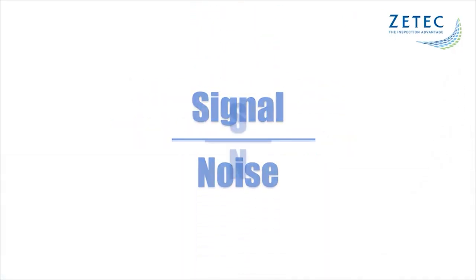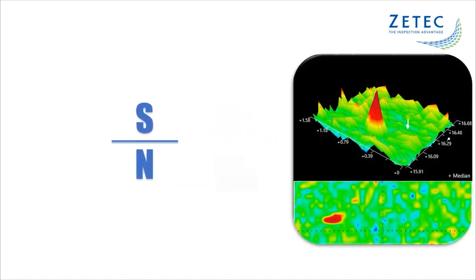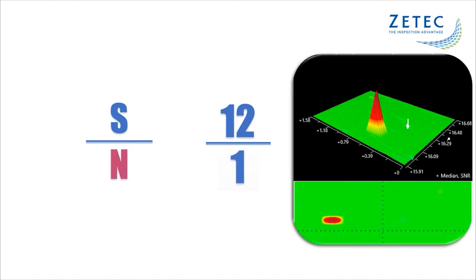The signal-to-noise ratio, or SNR, is a large factor when determining POD. When you are trying to detect very small flaws, or when you're inspecting areas in which there is a lot of background noise, the SNR may be quite low, as you can see here. Well, what if you could reduce the N part of the equation to give your SNR a boost?